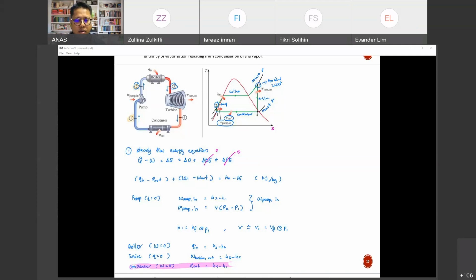and delta E basically equals delta U plus, if you look over here, we can cross out delta KE and PE because the kinetic energy influence is very, very minimal, so we can cross it out. And potential energy is also very minimal because it doesn't involve much change in height. From here, we can expand our equations to Q in, Q out plus W in, W out.